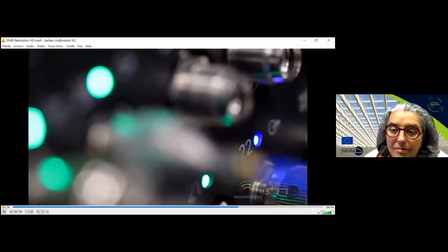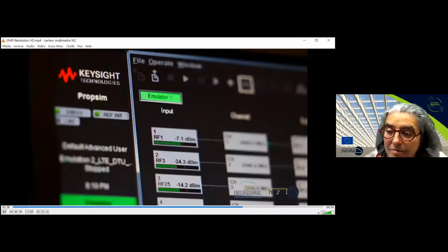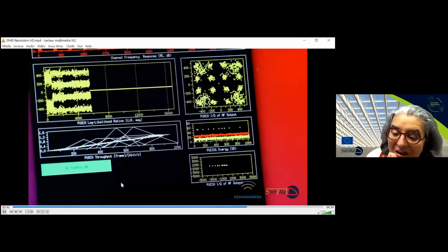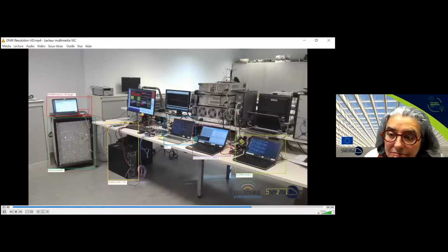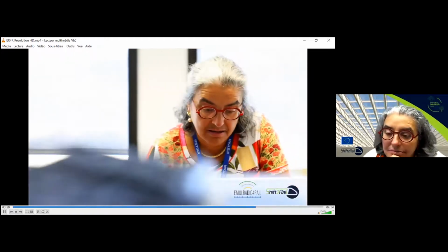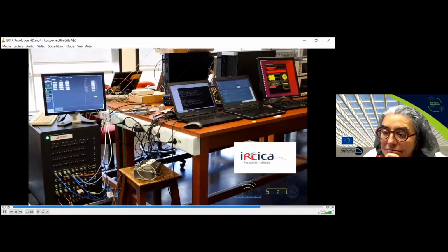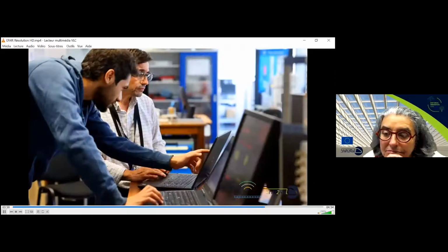The project has selected a set of 5 specific channel models for railway environment, including tunnels. We have verified that each platform works correctly individually in each partner lab. A big challenge was to integrate all the bricks of the platform together in a unique location at IRSEEM and to connect all of them to the Keysight channel emulator with the right setup.